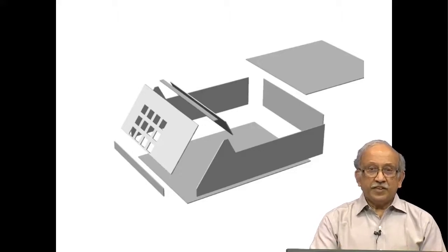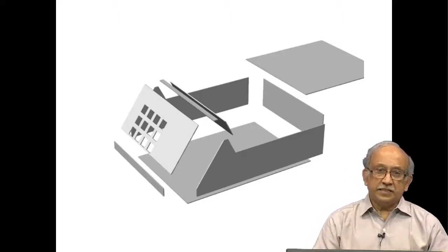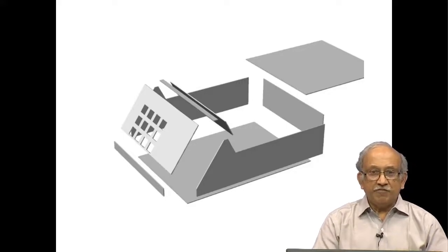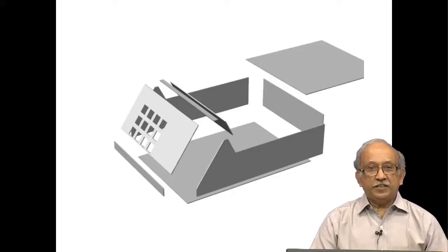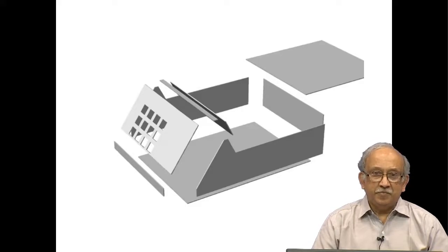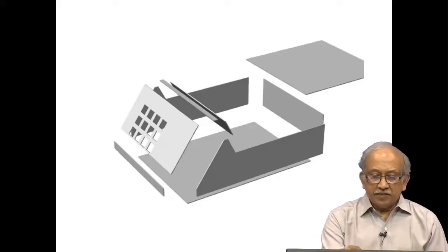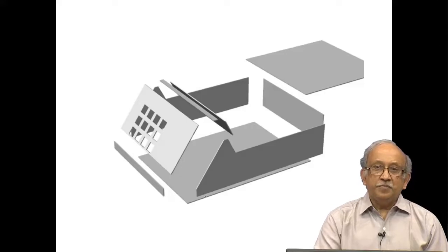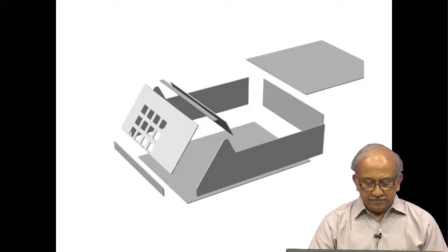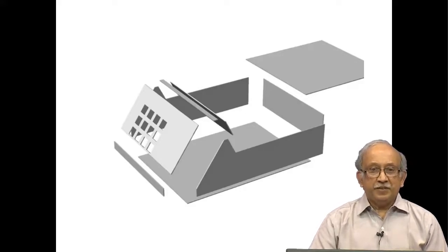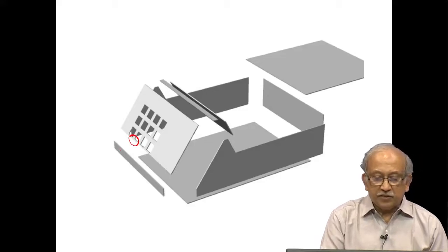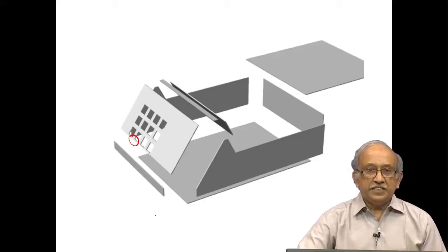Now, if you want to fabricate the same thing in sheet metal, one of the first things you need to do is find out how well you can spread all the parts inside. Is there some way of optimizing the layout? At a first level, it makes a lot of sense to break it up into parts which are flat, because by definition sheet metal things are flat. But you see here we have a little problem, it is very close to the edge, not easy to fabricate such things.